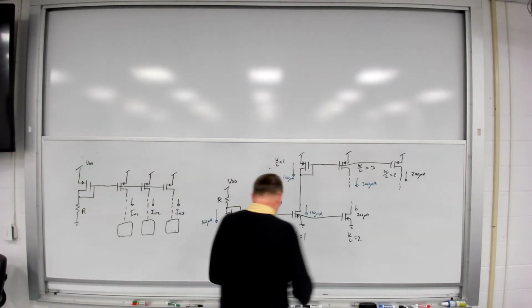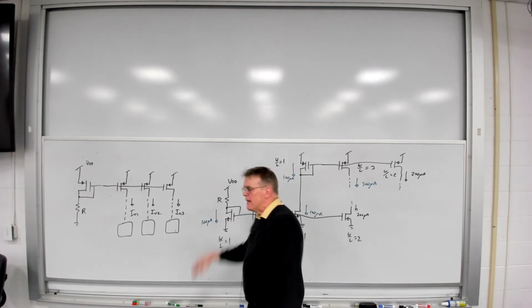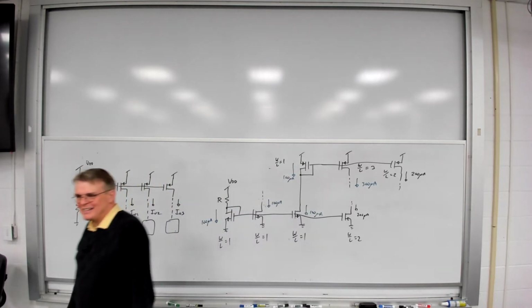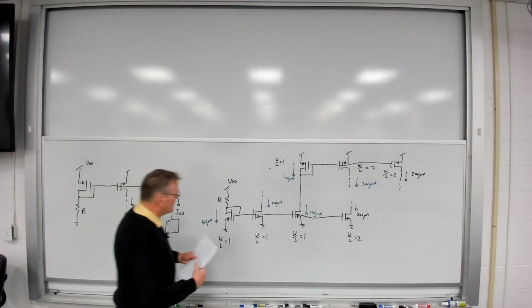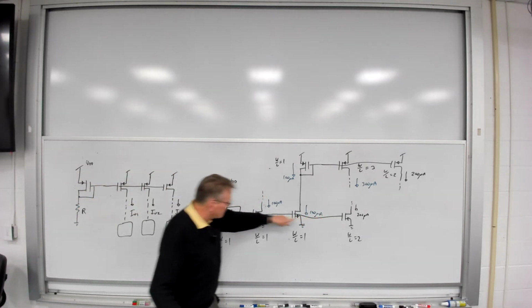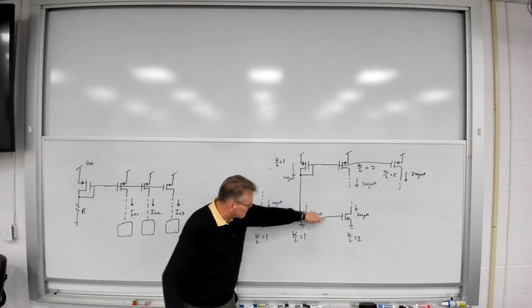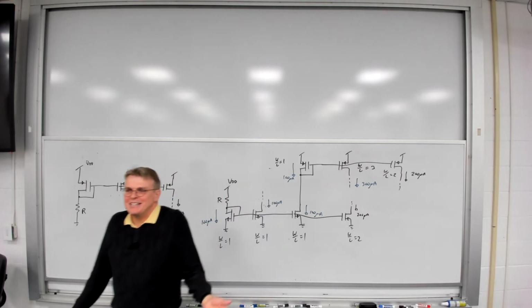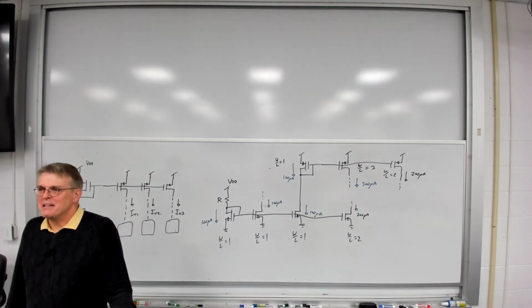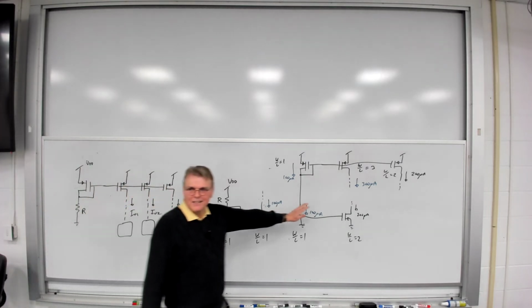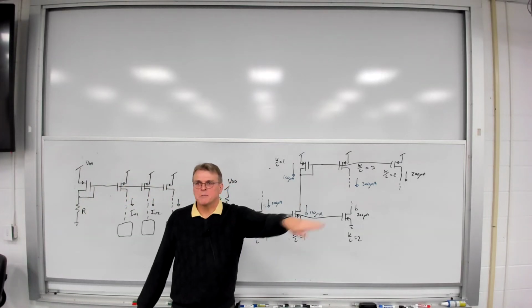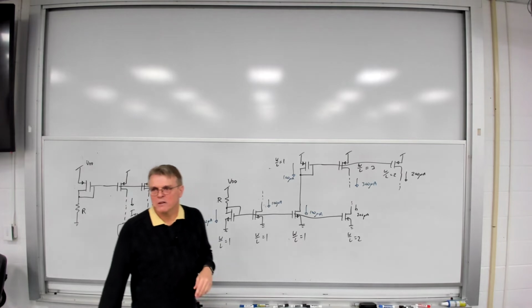Okay? This is incredibly common. Okay? You'll see this everywhere. Incidentally, what's the current flowing through these wires here? 0, yeah. You're just connecting into gates, right? So that the gates, there's no DC current at all. So that makes it very easy to extend this idea. All you're doing is you're just transporting a voltage, no current, across the chip.